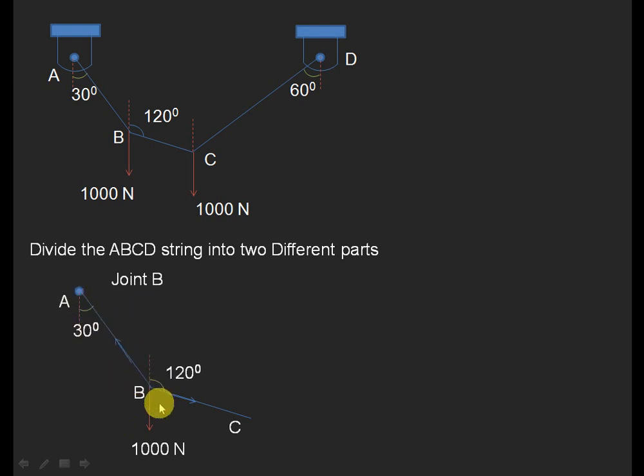and this line is intersecting these two parallel lines. According to the geometry of parallel lines, this angle is also 30, so represent 30 degrees here. Similarly, the vertical line is a total of 180 degrees. If you want the angle between the load acting line and the AB string, you need to subtract 30 degrees from 180 degrees. So 180 minus 30 ultimately gives you 150 degrees.